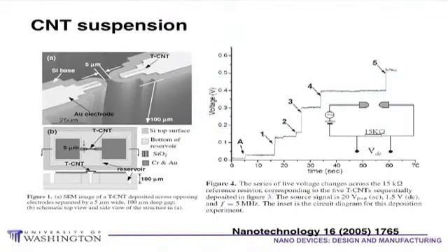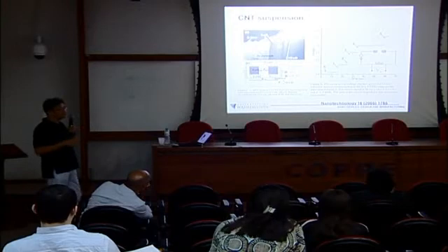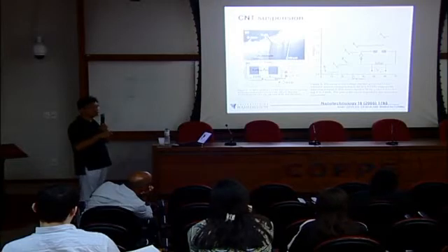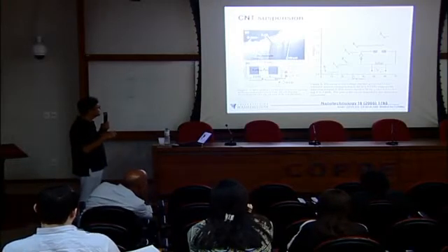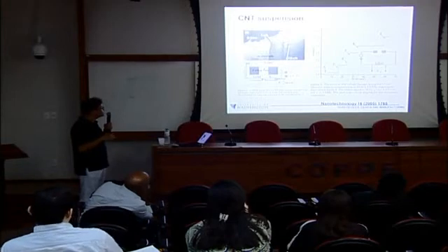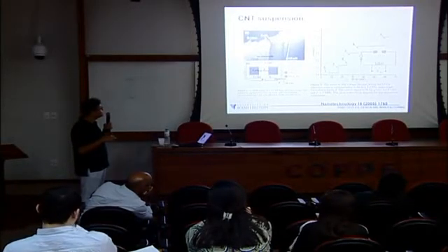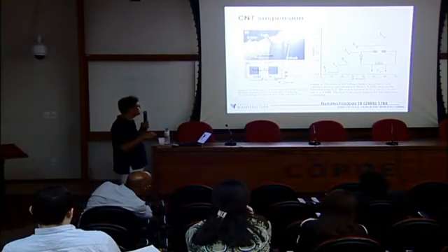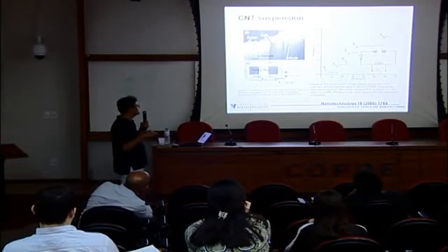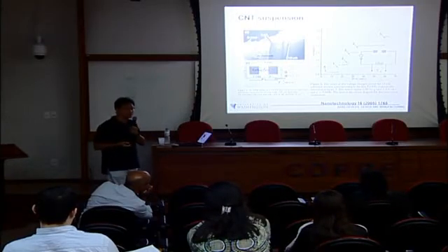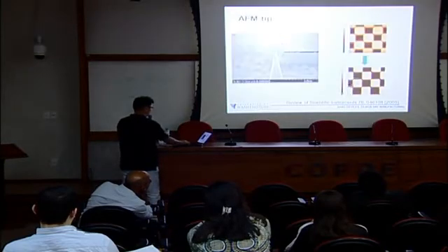And I showed you the picture of this tensile test device for nanowires. For this case, we have to precisely assemble the nanowire. Then we apply the direct forces to assemble one nanowire. Also the deposition process can be monitored by measuring the resistance in between. Once one nanowire comes in, the voltage increases because of this resistance. Then a second comes in, and again it increases, and third, fourth. So we can count how many of them. When one comes in, we can blow out the solution. Then only one nanowire will span, and that can be tested.